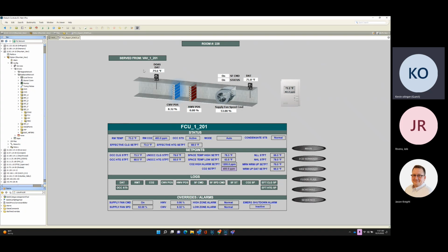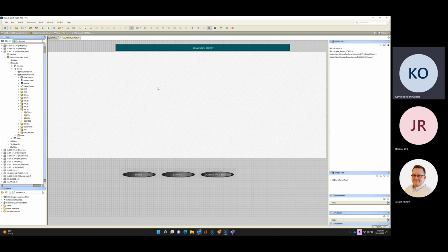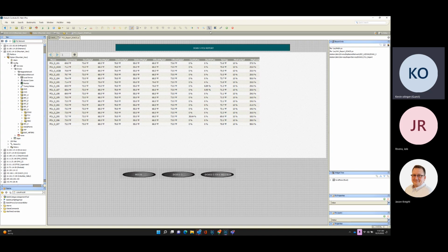So you're saying let's take this as a classroom. Room 228 has a VAV box up in the ceiling, and that's from our DOAS unit providing minimum outside air, and it's at the variable volume. And then also above the ceiling, there's going to be a fan coil unit that provides more of the zone's specific temperature control. Is that a fair assessment of what you're telling us?